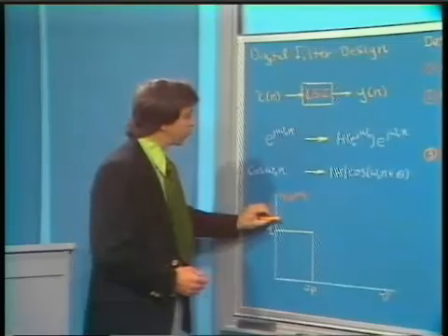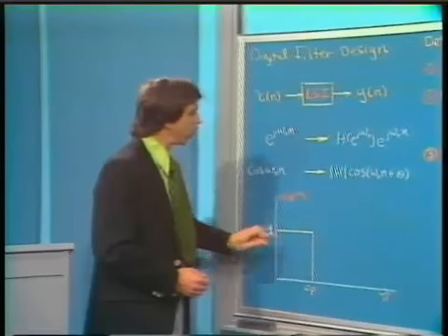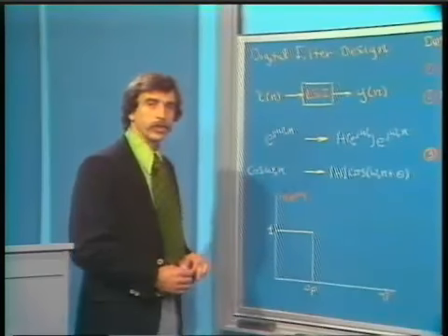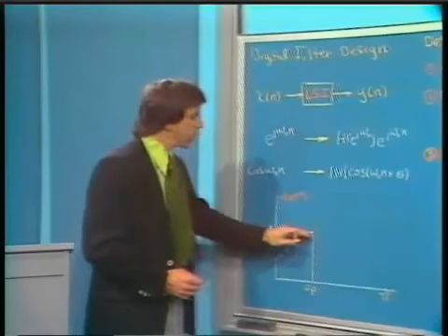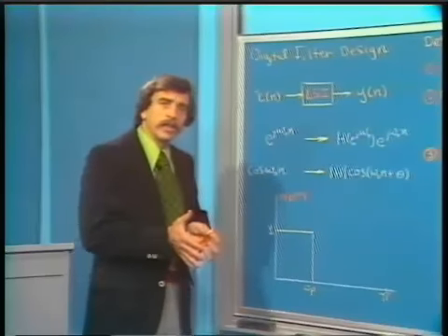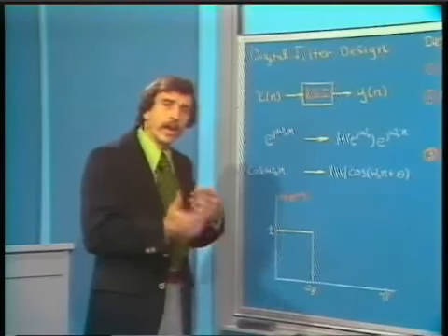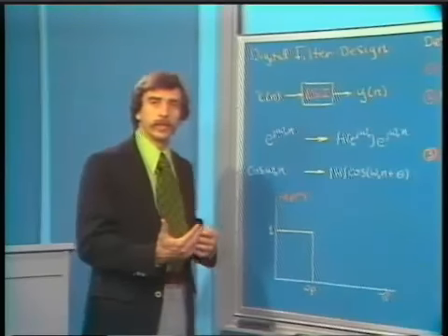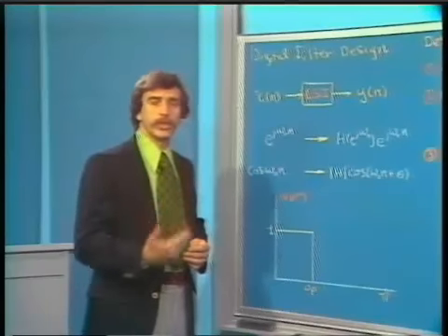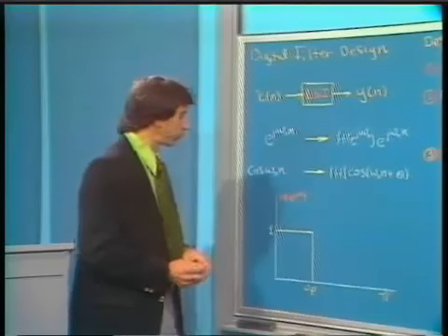So in fact, what's required is to approximate this ideal frequency characteristic, and the approximation of the ideal frequency characteristic and the design of a rational transfer function to implement that approximation is what the digital filter design problem is about.